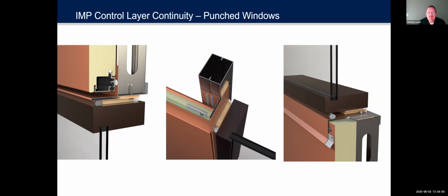Now, what you're probably seeing, if you know what you're looking at, is thermal bridges. You're seeing that metal going from the outside face to the inside face. And here you've got this perfect thermal barrier of an insulated panel, but at these window conditions, now I've created thermal bridges. So this is one issue that you have with an insulated panel. Typically you've got to have windows, you've got to have doors, you've got to have other materials. So how do you deal with it?